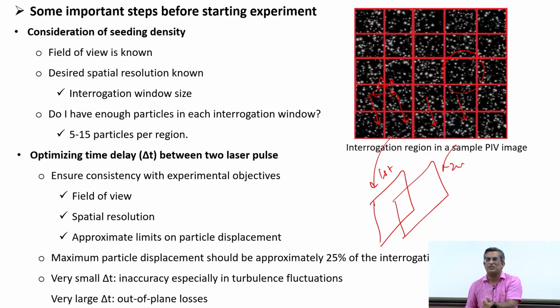So, the spatial resolution must be smaller than the scale of the turbulent eddies that you want to resolve. Now, if this spatial resolution is somewhere between the Kolmogorov scale and the large eddy scales, then you naturally filter out the small scales. So, inherently you impose a filter, as in the case of LES. But in LES, we model the rest. Here there is no modeling. So, basically you will not be able to capture the eddies below the spatial resolution. So, that is the point.